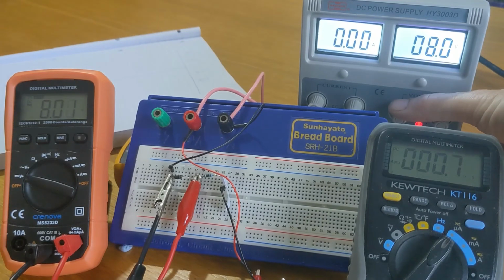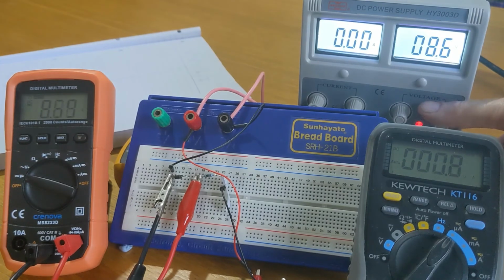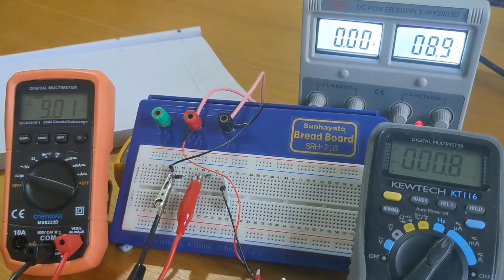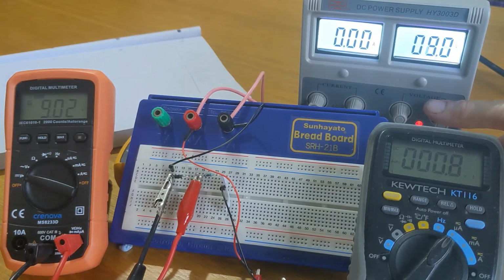Now there may be a bit of a pattern developing with the results, but you'll be able to show that on your graph. Obviously with very different scales required for the reverse bias recordings as there will be for forward bias. I could keep going volt by volt, but there really isn't a great deal to be gained by doing so. I do not intend to go as far as the approximately 35 volts which was suggested on the data sheet would be the breakdown voltage for this particular diode.